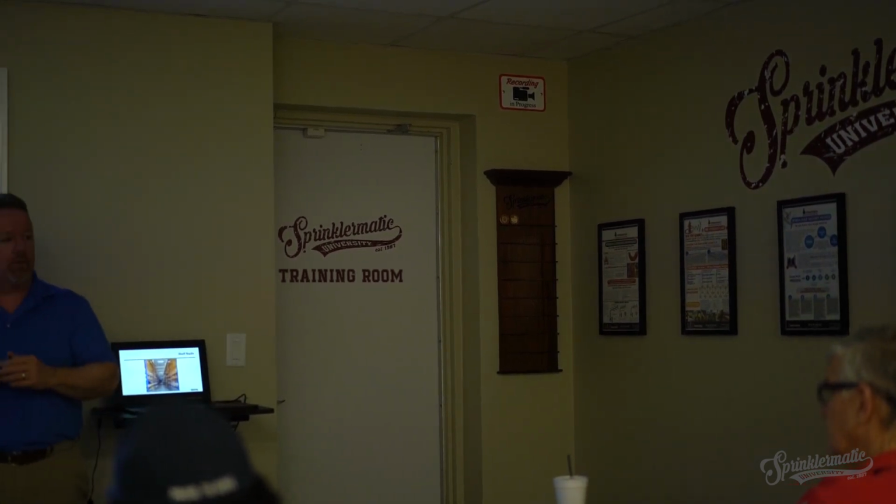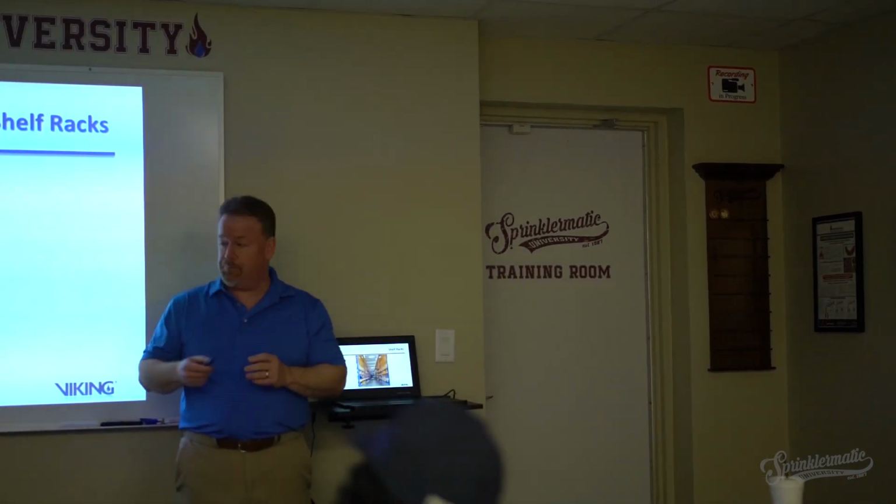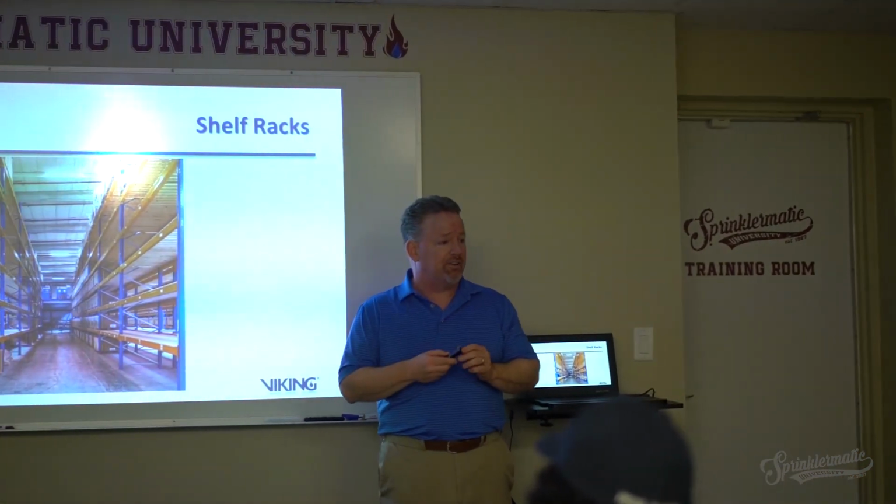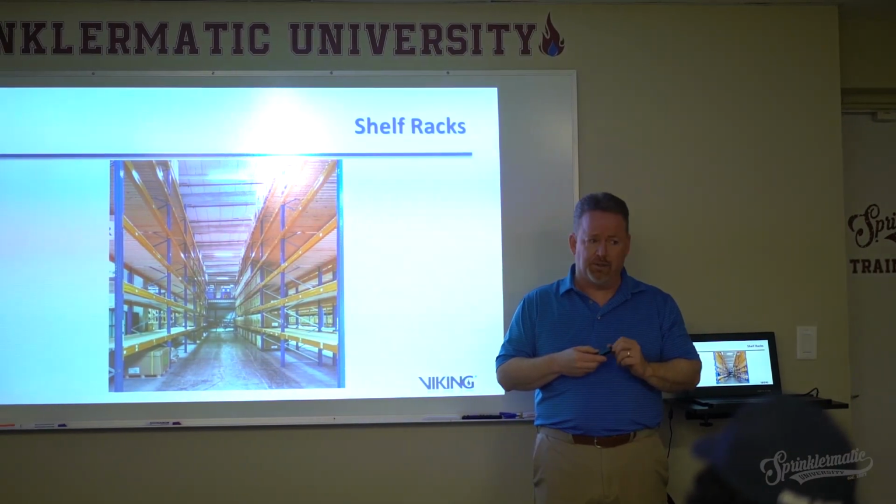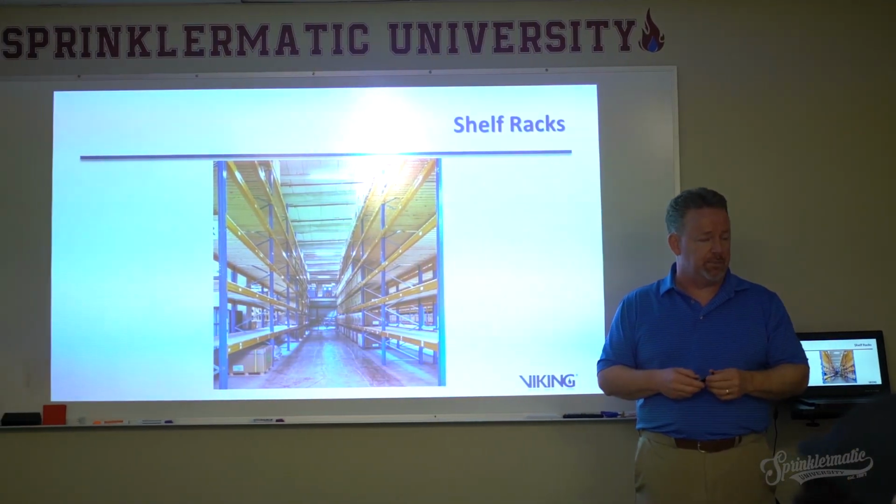So basically, what we're doing here is, typically when I have solid shelves, you're going to wind up with in-rack sprinklers in those locations. There may be times when there may be designs that are using those shelves as barriers and intended to be there. But yeah, a solid shelf, you're going to wind up with in-rack sprinklers. If you don't see in-rack sprinklers in a situation like this, that's a red flag. Find out, consult with the designer, what was the design intended to be.